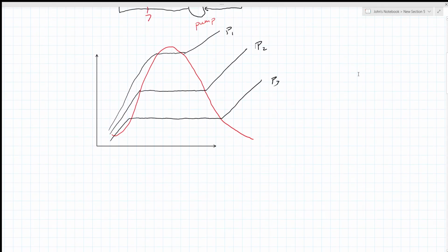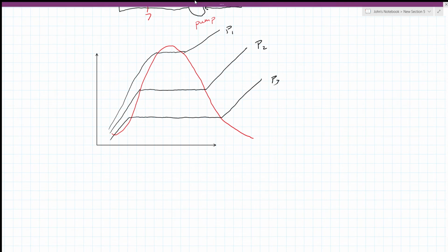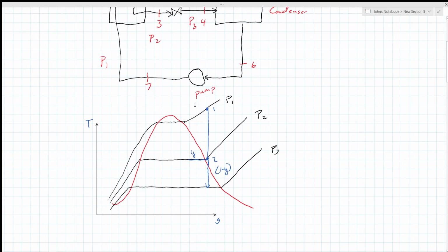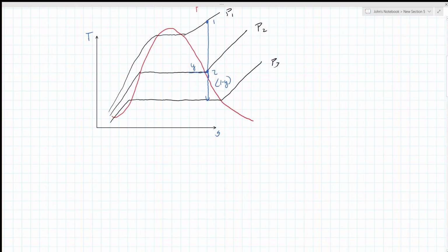So, like I said up here, this is water freshly out of the boiler, so it's steam. Right here, I'm at 1. So I flow down here going through the first high pressure turbine, state point 2. Some is siphoned off that way. The rest goes down through the low pressure turbine here at 1 minus Y. This here is labeled 5, so this is 5.